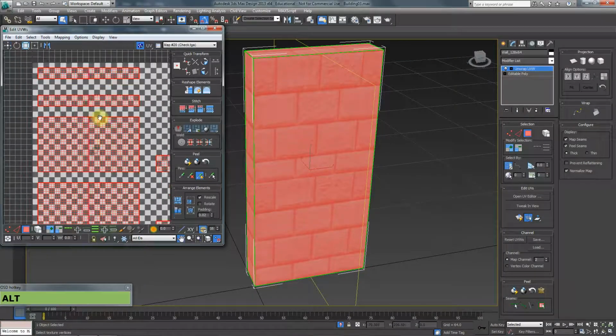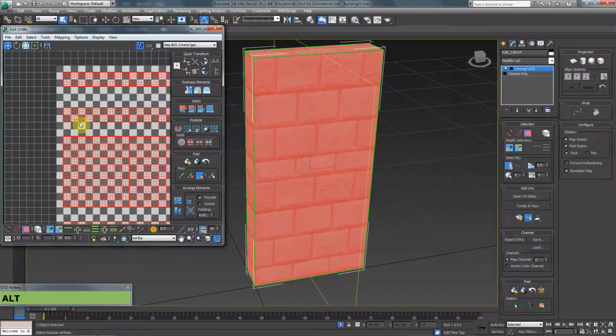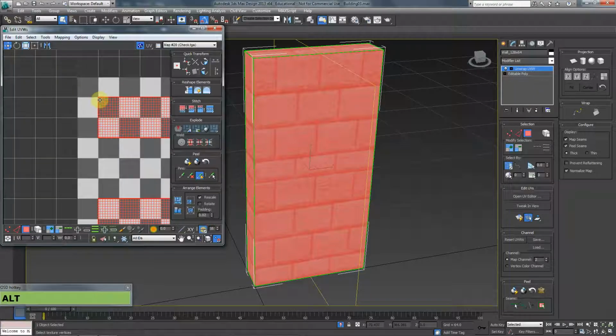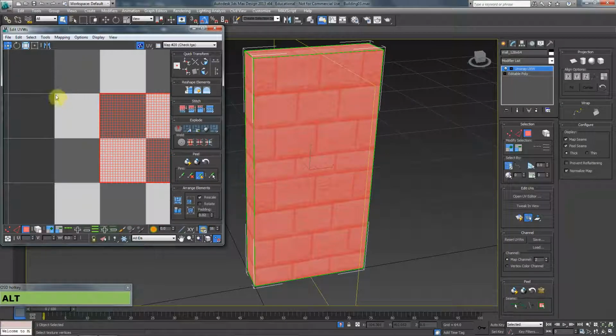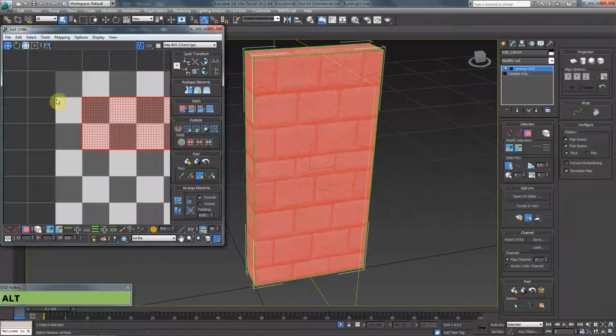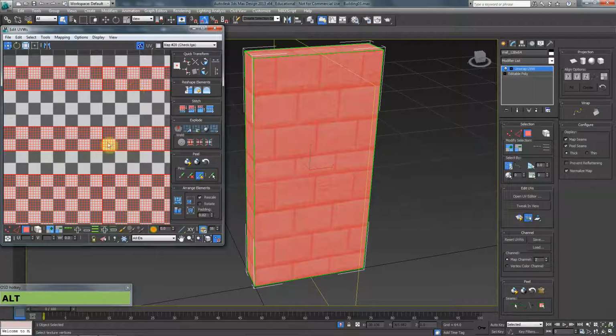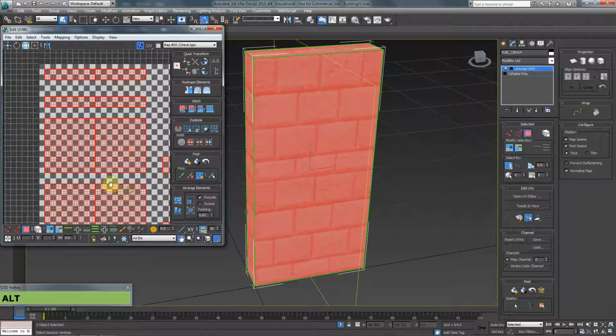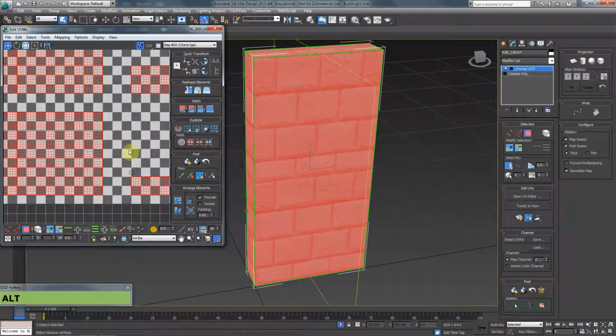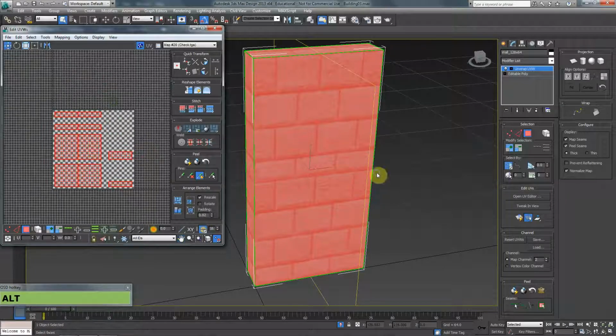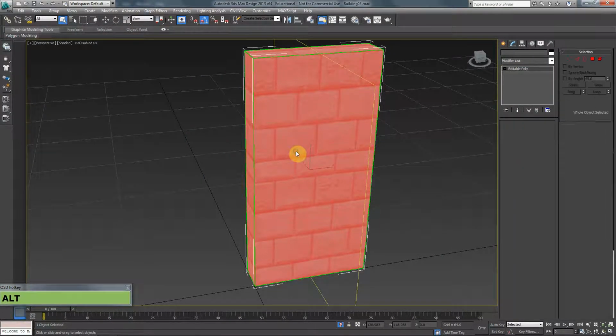So one thing to have in mind is, number one, make sure you have at least 1 pixel distance from the edge of the grid. So don't put this here, make sure there's at least 1 grid distance. And between each of these islands, make sure you have at least 2 pixels. In this case I have 3, here I have 2, here I have 2, again here I have 3, I have 3 here. So this is good. Once I'm happy with this, I can say convert to ideal poly. That's done. So I will do this one more time.